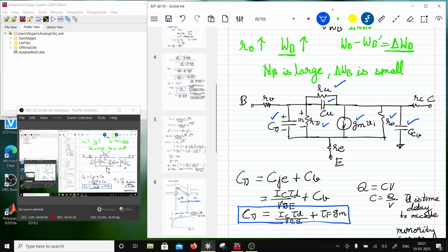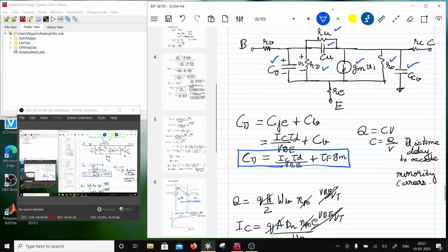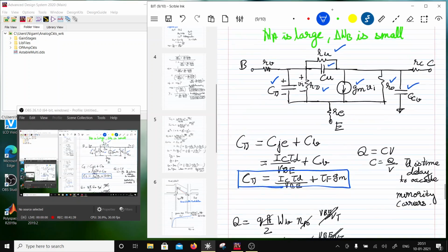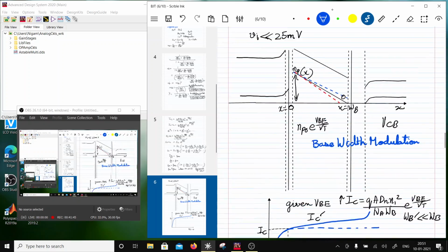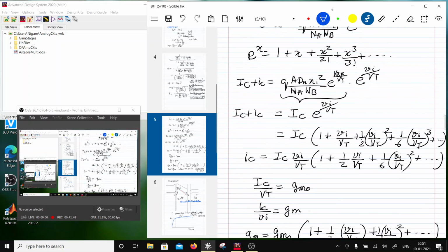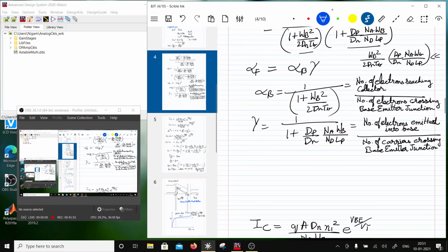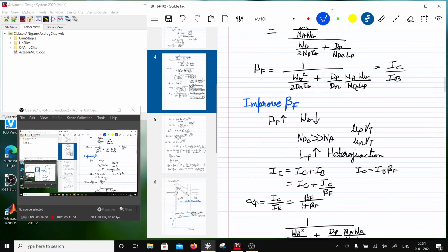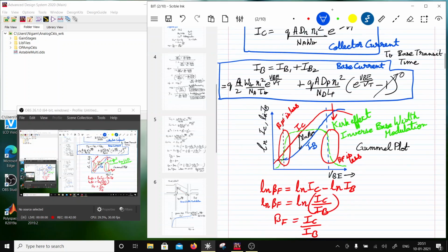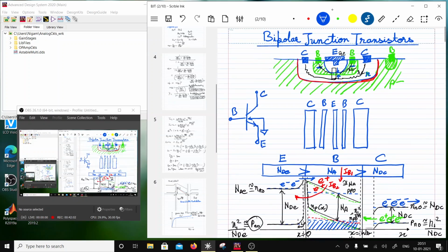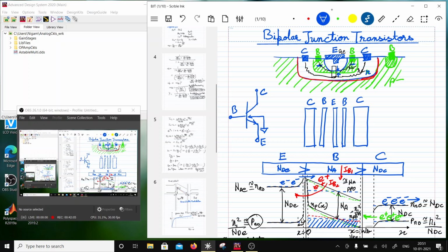So now we have covered this, and what we are left with now is the extrinsic resistances. Now this is very important. Why it is very important, I'll explain to you. This is something which every designer should know. When I say emitter periphery, I am really not referring to the area of the emitter junction. I'm referring to the perimeter of the emitter junction, which is more important than the area. So if I go to the construction, when I say emitter periphery, what's going to happen is there is a base, right, which is basically distributed, but the real base is over here.